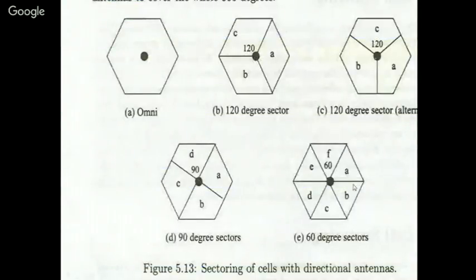So these are different types. This is the omnidirectional, not available in the case of the audio. At 900 megahertz you cannot make omnidirectional. So make the 120 degree, covering this area using 3 dipoles. This is another way, same thing: either put this way or put this way. Or make the 90 degree or the 60 degree. So there are different ways of covering the area.